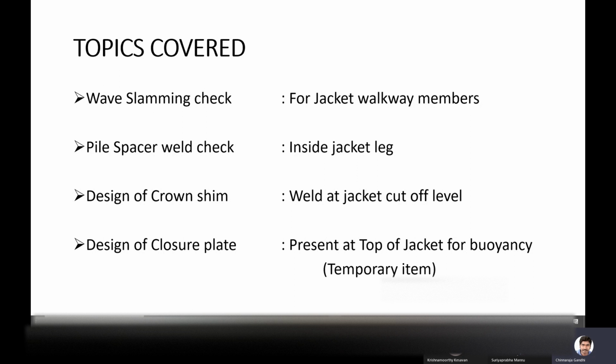Whenever there is a lateral force, the lateral force will be transferred to the jacket, and the jacket will transfer it to the pile through the pile spacer. So we will check how we have to design the pile spacer, and what is to be checked for the pile spacer.